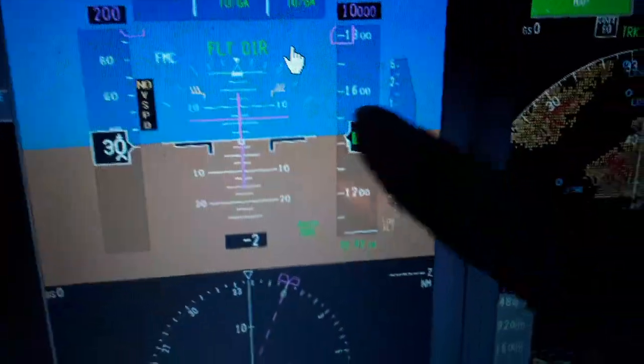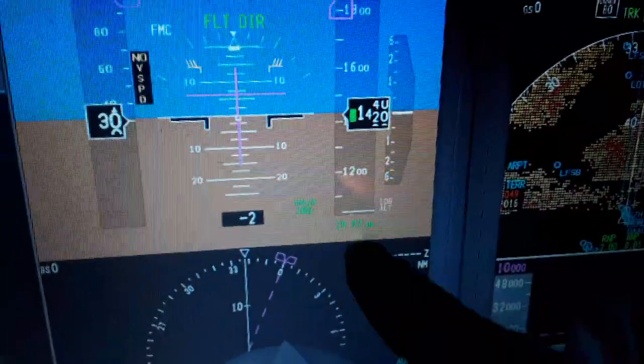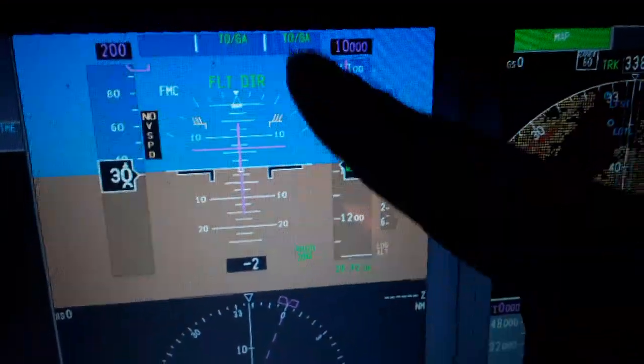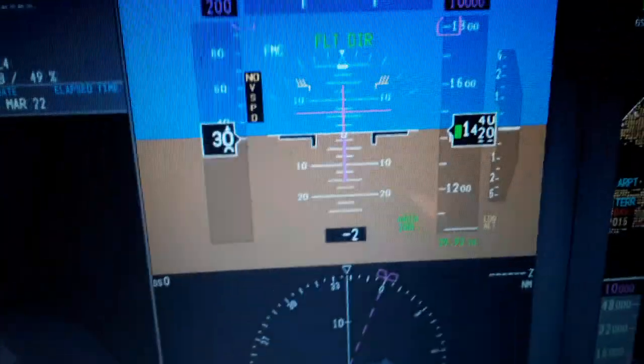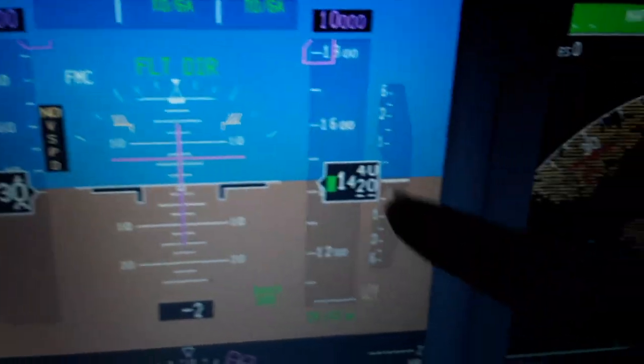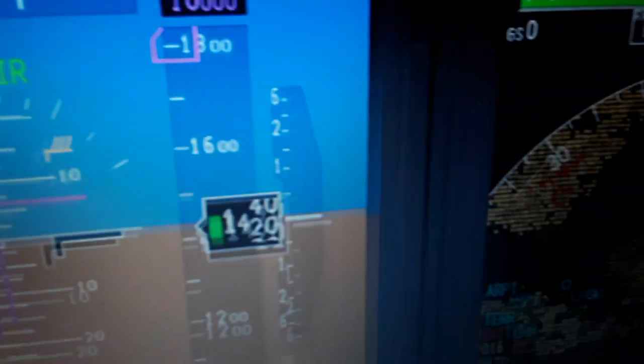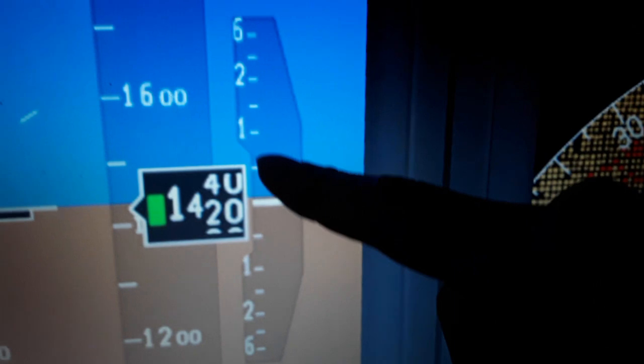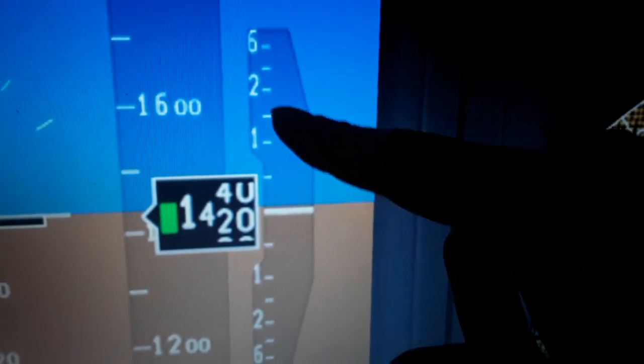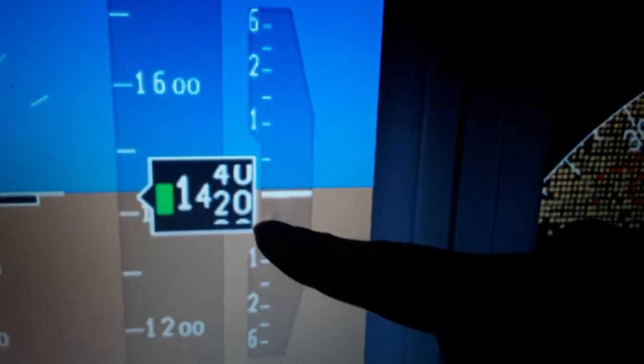So you can see here we have the airspeed indicated, the airspeed tape, the airspeed selected from the autopilot flight director system panel, the barometric altitude above the sea level, the barometric pressure of the outside atmosphere, the target altitude selected from the autopilot flight director system panel over here. Also the vertical rate of climb descent of the aircraft, index 10,000 feet per minute. All the steepness, trigonometric angles increase. You can see 500, 1000, 1500, 2000, 3000, 6000 feet over here, climb descent.